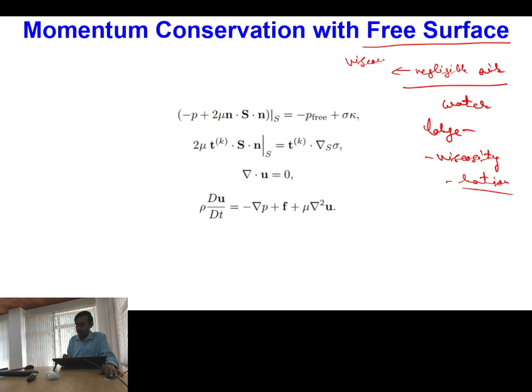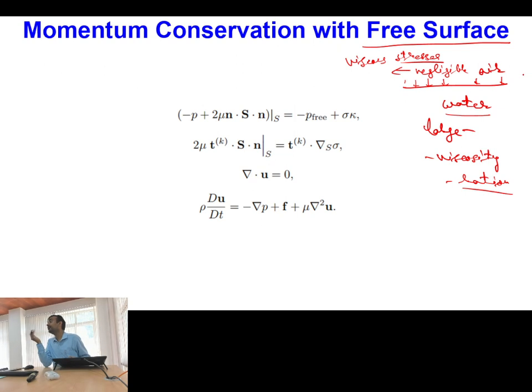Okay, so viscous stresses in a low viscous medium will be negligible, and the value of pressure will be specified in this low viscous system for free surface flows. Whenever your interest is only to see the dynamics of water, you are not much concerned about the behavior of air. Under that scenario you can take advantage that your interest is only to see how your free surface is evolving with space and time.